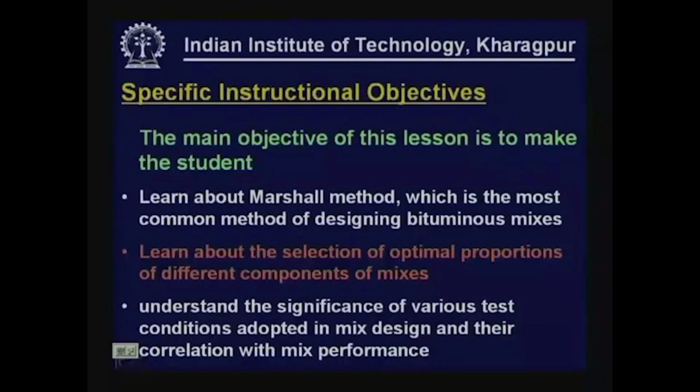So, we would like to discuss Marshall method of mix design, which is the most commonly used method for designing bituminous mixes. Also learn about the selection of optimal proportions of different components of mixes, what should be the guidelines that we should adopt in selecting optimum bitumen content, having selected what is an appropriate aggregate skeleton, aggregate gradation,